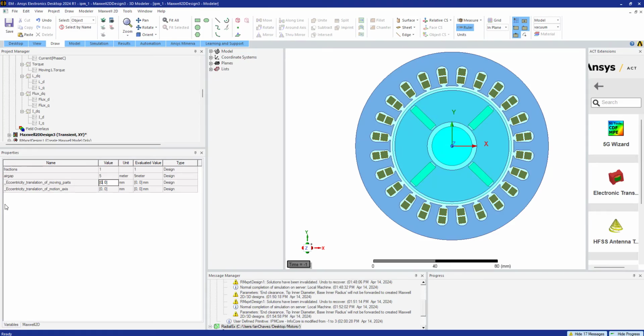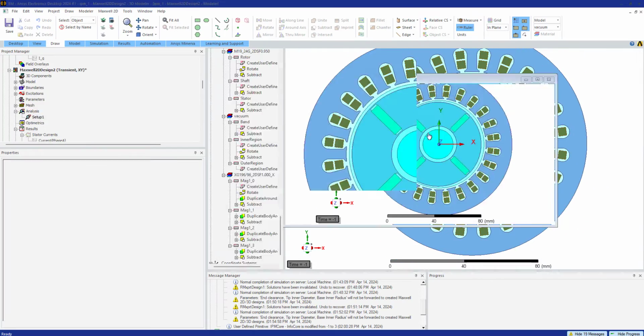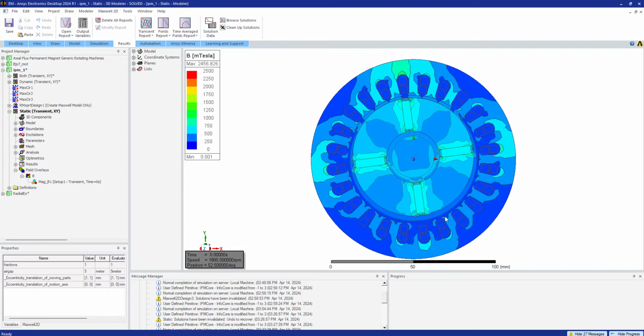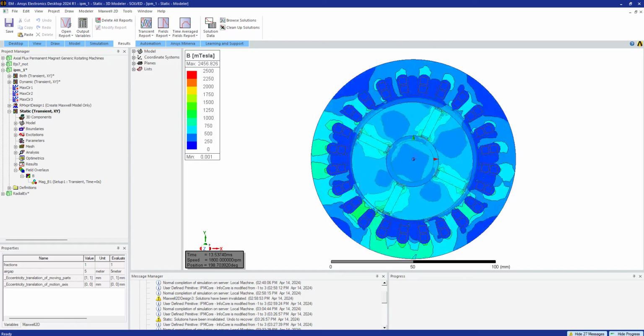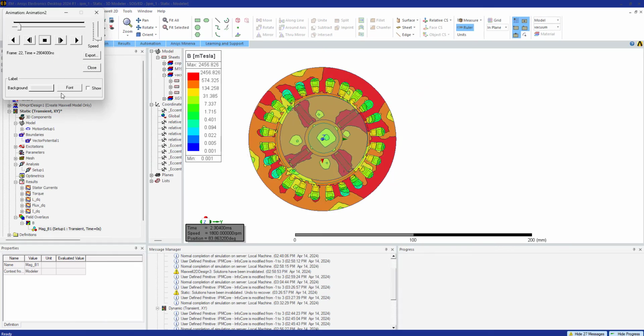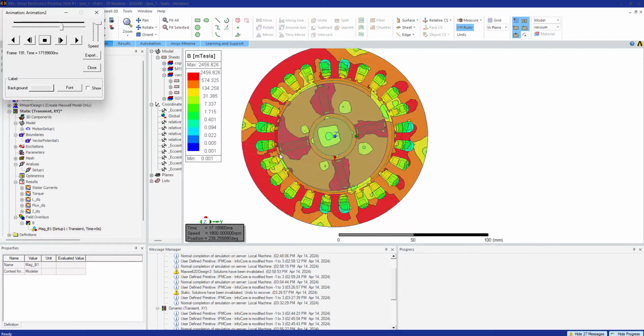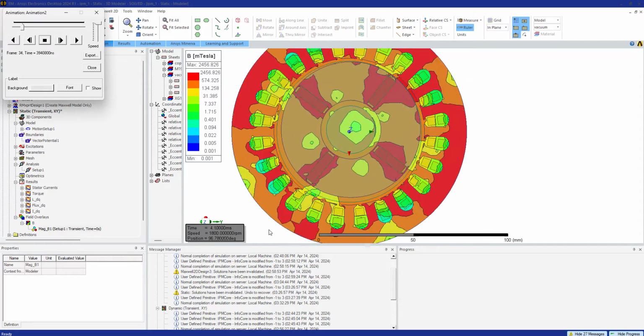In the new model, you'll find variables where you can set the vectors for the rotation and the rotating axis. When you set values for these vectors, you can see the model shift accordingly. Here's an example of a dynamic eccentricity simulation. Notice how, as you would expect, the area with the smallest air gap has the highest magnetic field. For this one, I set a vector on the rotating part, but not on the rotation axis, so because they're mismatched, we've got the mixed eccentricity case.